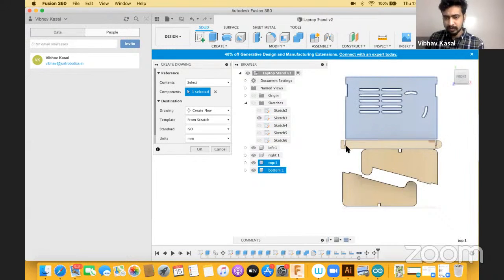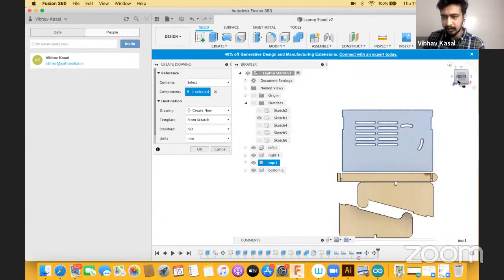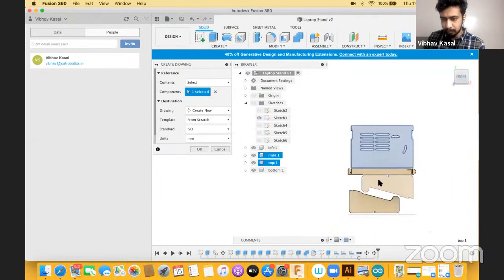So what happened was there is a line here. When I laser cut, it will cut through here also. Every line it will cut. Every edge that it shows up, it cuts. So probably this is a mistake, but I'll cut it anyway, and then I'll try to fix it again in later stages. Because now that I know I can create any body of any shape, any size, I can make changes. Then I'll simply hit OK for now, for the time being.